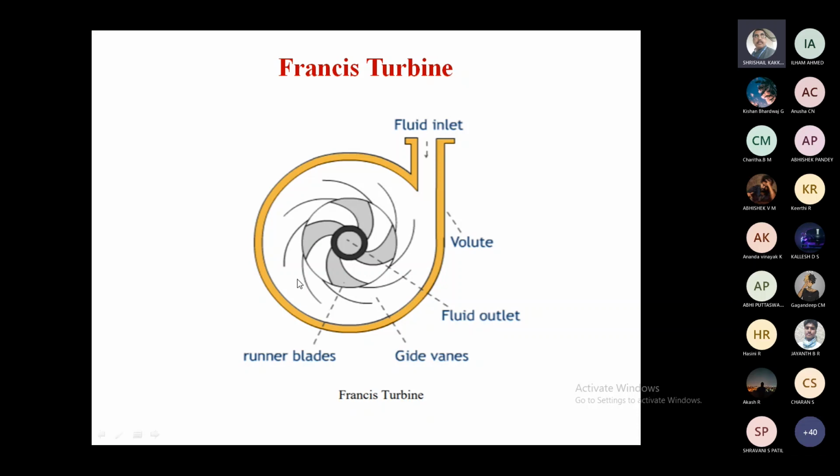The curved vanes fixed in the casing act like a nozzle while the water is entering, because the cross-sectional area is maximum, and as it comes here, the cross-sectional area becomes lesser. Guided water, without friction, enters the runners or running blades. So here the reaction happens, so that the runner starts to rotate at very high speed.